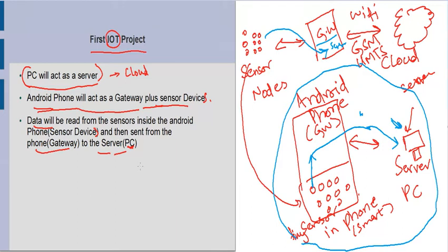Again, I can describe once more. For example, we have described two kinds of topologies, right? One of the topologies is this one, in which the sensor nodes are separate. In between is a gateway, and then we have this, our cloud. The values are read from the sensor nodes and sent to the gateway. The gateway, which can be anything, our phone, or a Raspberry Pi or Arduino based gateway, is going to process those values or filter them and send them to the cloud.